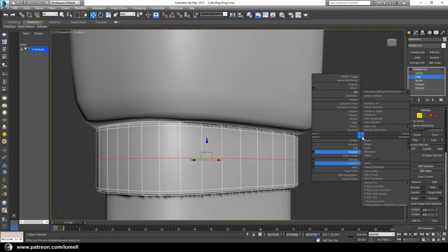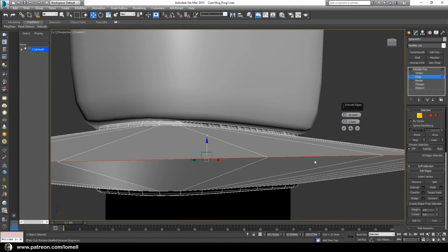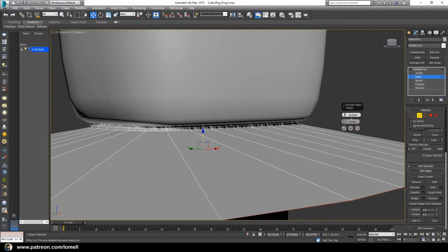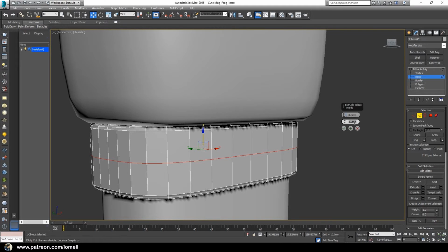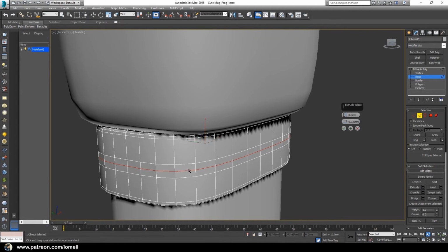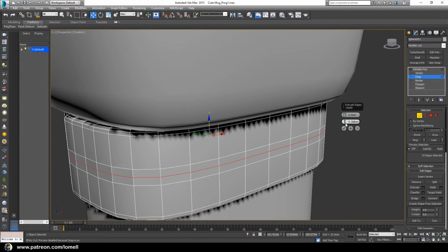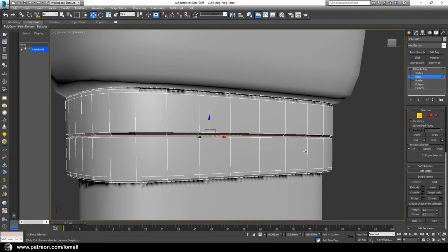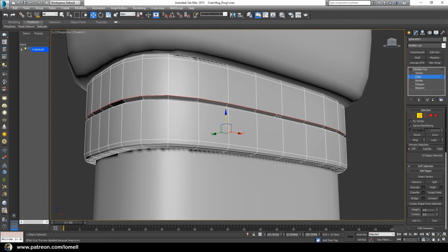Right click and choose this box setting under extrude tool. In extrude tool, let's set these parameters to 0 first. Everything should be 0 first, and now let's try adjusting this arrow by dragging that. It's going to add additional segments out of these segments at the center, so we have to give it a little distance. Now let's try adjusting this arrow and pressing this down arrow here. If you're done, click this check icon.